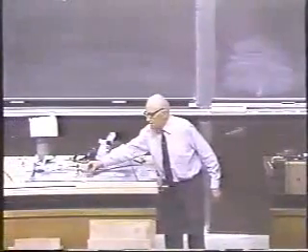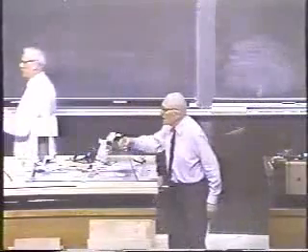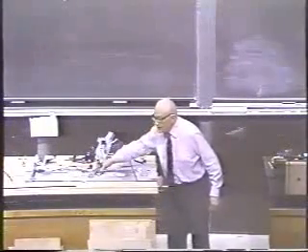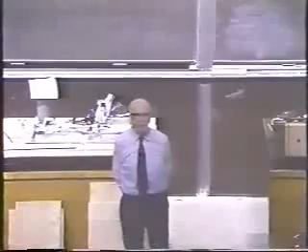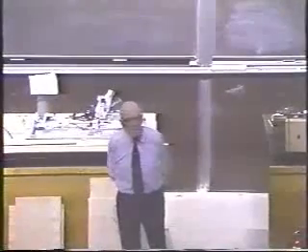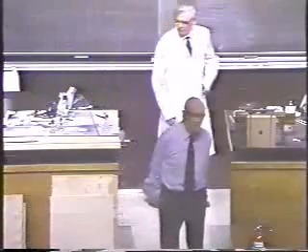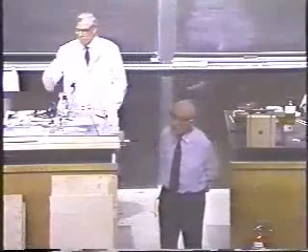Well, as I say, it is an example of an application of explosive impact moulding, which is a very useful process because, you see, it's very cheap. If you wanted to mould something, you'd have to set up a very expensive press to do it. But here, a few pence worth of explosives will do the job.